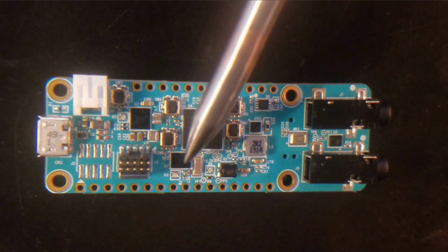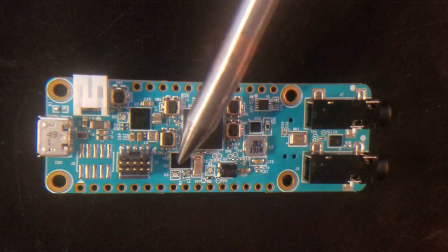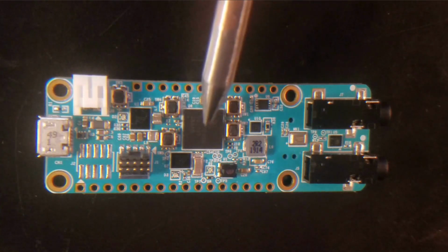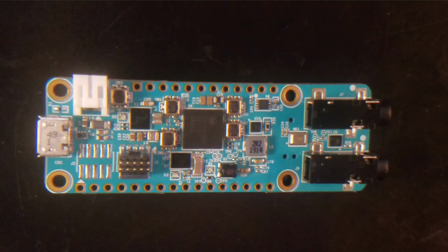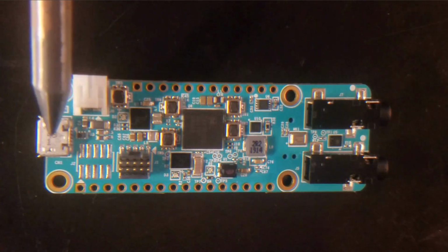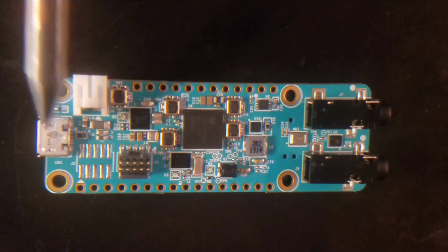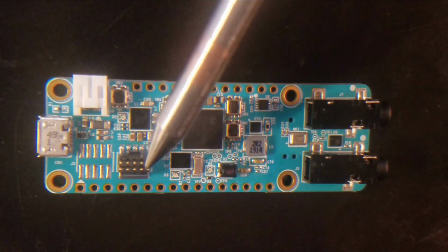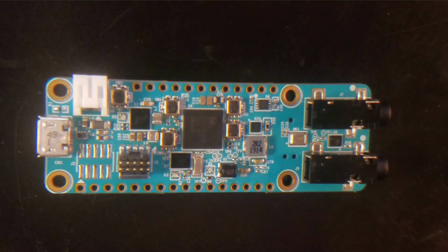Moving left, we have the MAX32625 MCU that serves as a DAP-Link debugger for the Cortex M4F core and the MAX78000. The debugger exposes a DAP-Link interface, flash drive interface, and a UART interface on this USB port. This header is used to debug the RISC-V core in the MAX78000. You can connect an external adapter such as an Olimex to debug the RISC-V core.